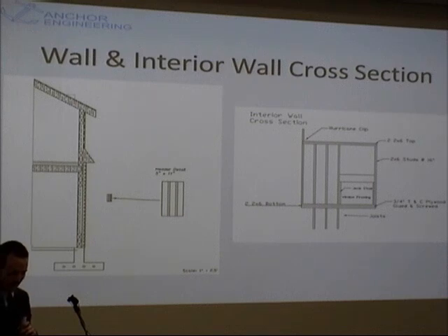I designed the header to be 11.5 by 11 and a quarter by 5.5. This was done for the deflection and the support of the studs, which were calculated to be 2x6 at 16 inches. To the right is just a wall section showing the support and the studs.